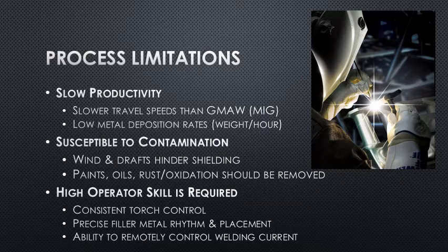And that can also be a curse because it's one more thing, like I say, to have to pay attention to. And oftentimes people tend to weld like they drive a car, and they go all the way to the floor. And that's a bad thing when you're driving, and it's also a bad thing when you're TIG welding because usually you make holes in your material.